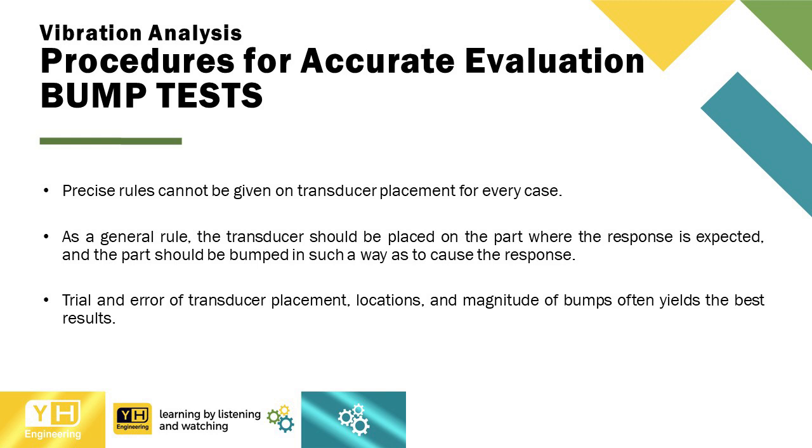As a general rule, the transducer should be placed on the part where the response is expected, and the part should be bumped in such a way as to cause the response. Trial and error of transducer placement, locations, and magnitude of bumps often yields the best results.